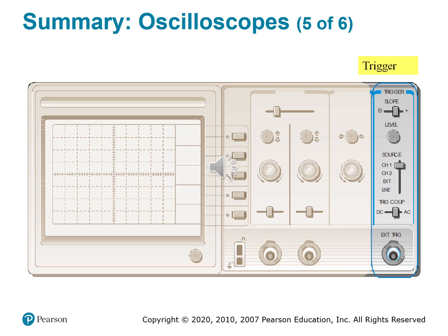The trigger level sets the voltage threshold at which the oscilloscope triggers. For example, you might tell the scope to only trigger when the signal crosses 2 volts going up. And you can fine tune this to capture signal transitions.